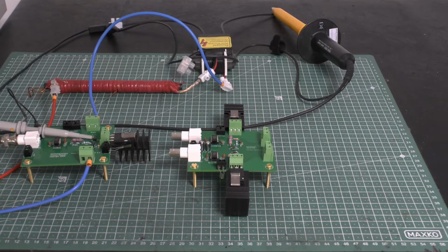It works as a kind of filter and also as a storage device, which allows us to have a smooth transition of power to the primary coil of the flyback transformer, and therefore we have a better transition to the secondary, which means we have a clean wave signal available which we can measure on the oscilloscope.